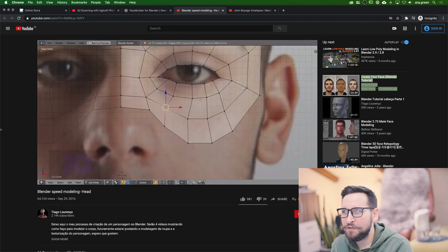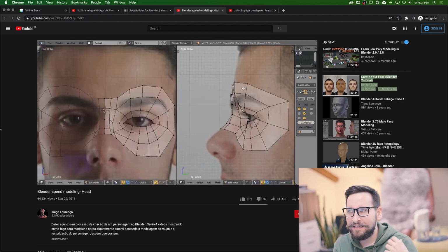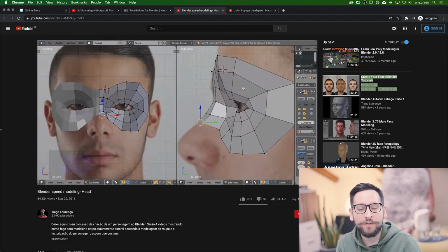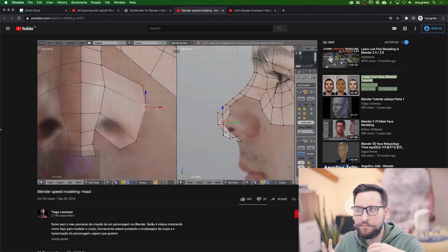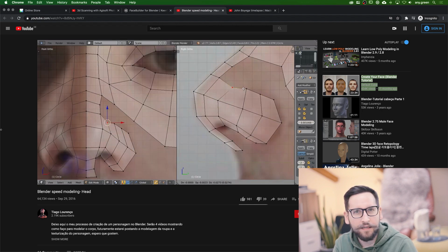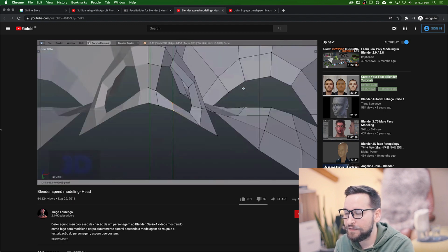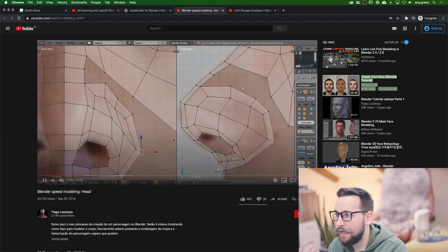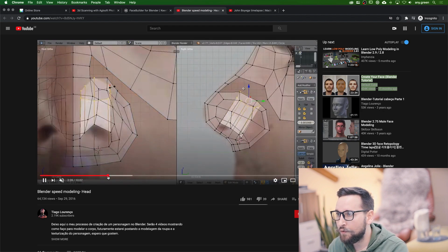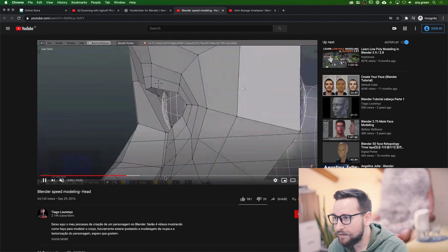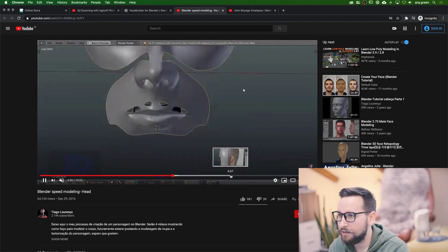Probably the first 2 or 3, 4 times that you do it, the results are kind of meh, but once you get the hang of it and you get the process of how you like to work with these polygons, you learn the tools of how to extrude them, merge them, create a quick mesh or bridge the polygons, like I showed in our last session, how we can bridge between two different rings or lines of polygons. You will get the hang of it, and with this you get the cleanest mesh, the most accurate mesh, and the most control over it later on. But this is very, very time consuming, as you might guess.